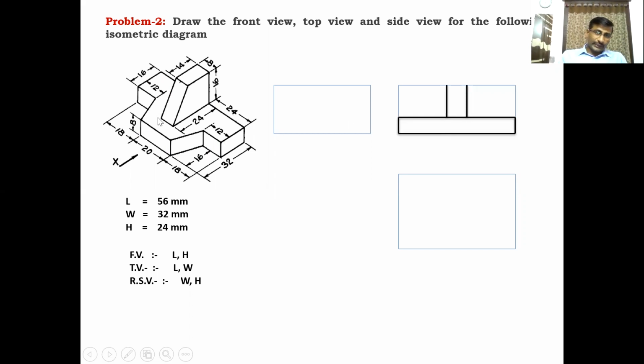And this is also a vertical line on the other side, and the distance between these two is 8 mm, and close it, 8 mm length. That is the horizontal line. Okay, and this inclined surface is visible as a vertical surface in the front, which is reduced in length.